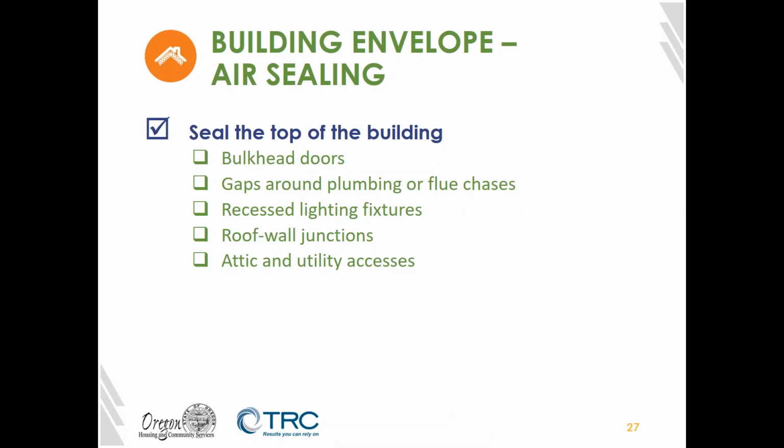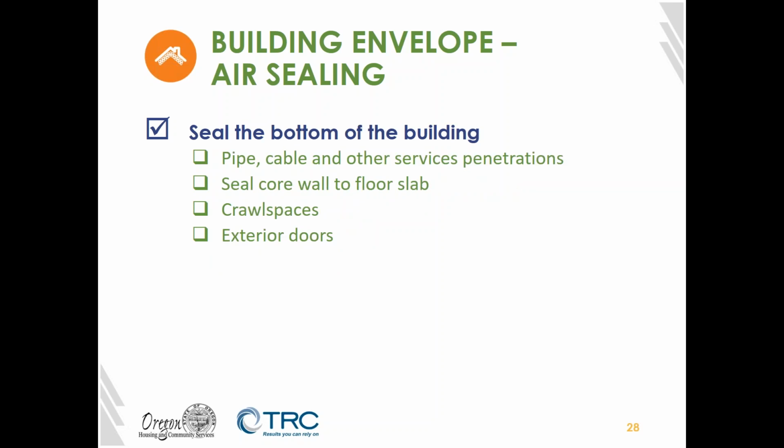So that's an idea about what we need to seal at the top of the building. Now, we also need to seal kind of everywhere else in the building, because remember, air will find the path of least resistance. So just because you've sealed one area doesn't mean the air is not going to find a way in or out of the building somewhere else. So we also need to seal the bottom of the building. I'm just going to pop through these very quickly.